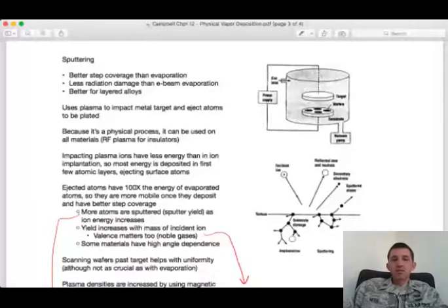So that I'm depositing a little bit of, say, metal 1, and then stopping, and then depositing a little bit of metal 2, and then stopping. So instead of moderating the temperature, I'm moderating the time that the wafer is exposed, right? So I could have alternating layers of different metals and then maybe have an anneal treatment at a later point that would enable those two different metals to kind of diffuse in amongst themselves and create the alloy that I'm going for.